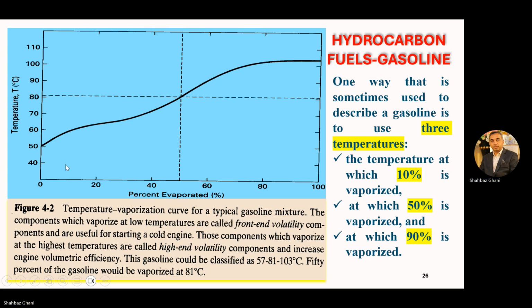Now, 10% evaporation is at 57 degrees, 50% evaporation at 81 degrees Celsius, and 90% evaporation at 103 degrees Celsius.